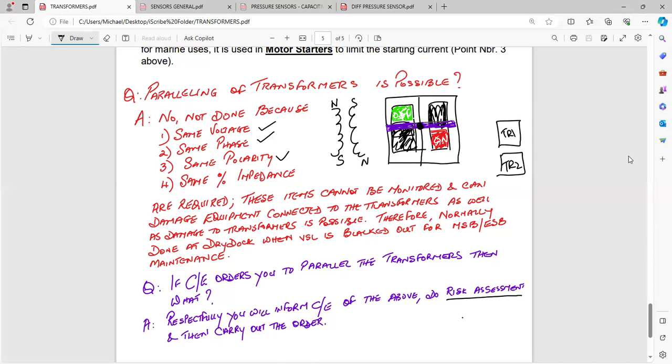Whereas for paralleling your generators, first and foremost, you can see the frequency. You can see the voltage on the panel. Those are the only things. But the phase sequence and all that is being monitored by your power management system. If your power management system was not there, then that check synchronizing unit would not have been there. There you have something to help you. Here you have nothing to assist you.